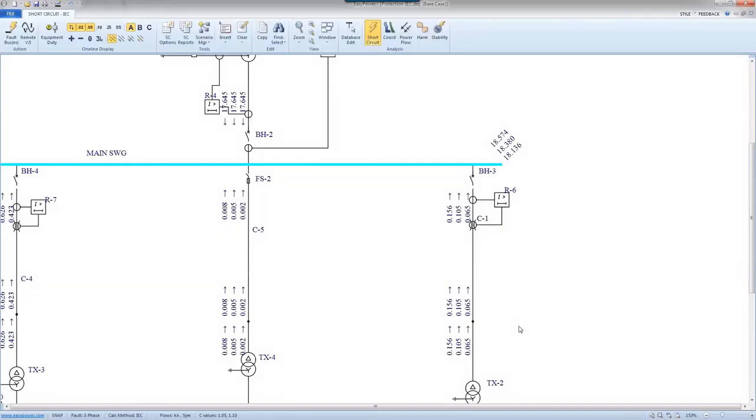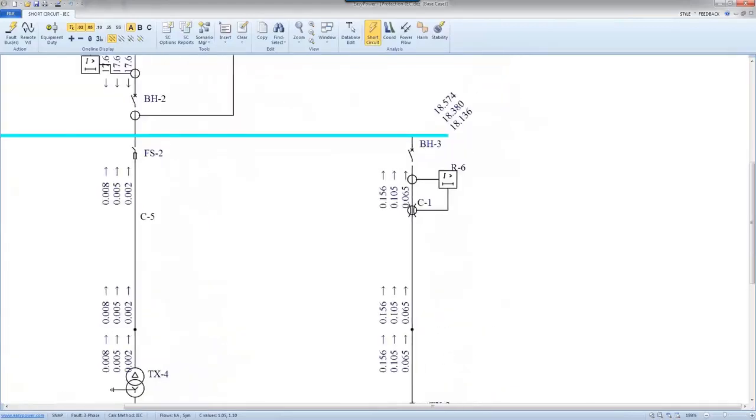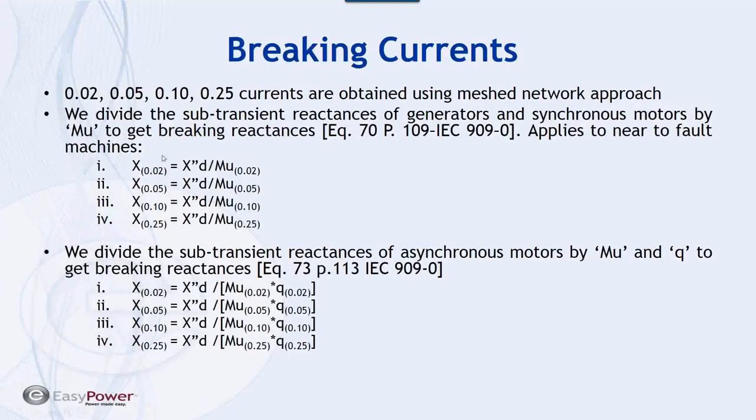But regardless of that, in order to see how we replace the impedance in those rotating equipment, let's go back to the slide and see what we do. For synchronous machines, so synchronous motors and generators, that's how we modify and adjust the impedance of the initial current. These values were the values that we use for initial currents. Then you would think that if there is a source which is supposed to have decay, decay means that the impedance has to go up.